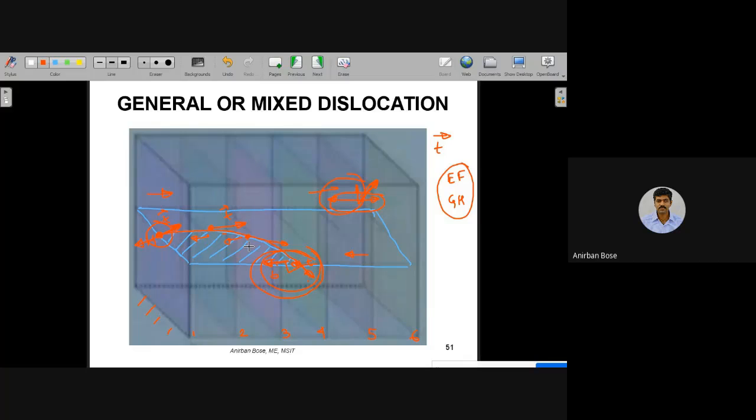Exactly as you know, in case of a Mohr circle, in case of principal stresses only the normal stresses are present. There is no shear. That is the case for the edge dislocation. Similarly, the pure shear, that is the case of screw dislocation. In other points of the Mohr circle, that is a general state of stress where both normal stress and the shear stress are present. Exactly the same picture is here also. Within the crystal, the strain field is distributed in that way around the line.